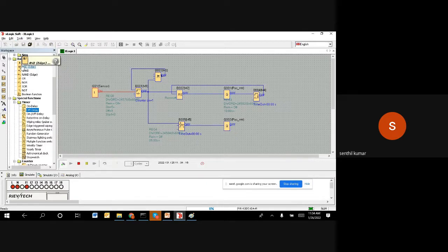Right? So now the bottle production count is 1. Only one bottle is produced. So the packing motor is not moving now, because it is not necessary, because the packing motor needs a minimum of 5 products to be inside again, right? Okay, 5 or 10, whatever. Like we consider 5 now, right? So I'll go for 2, 3, 4. Now 4 bottles are produced. So now if I produce a 5th bottle, you can see the outputs Q1 and Q12 both will become on.